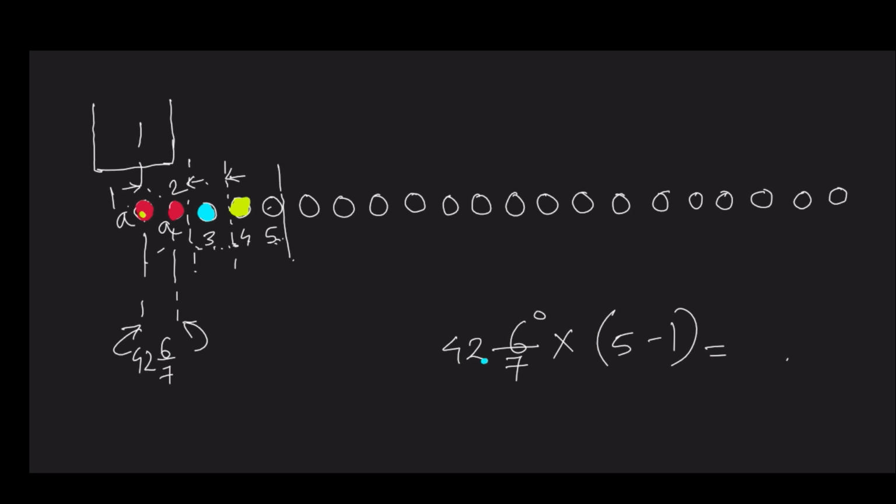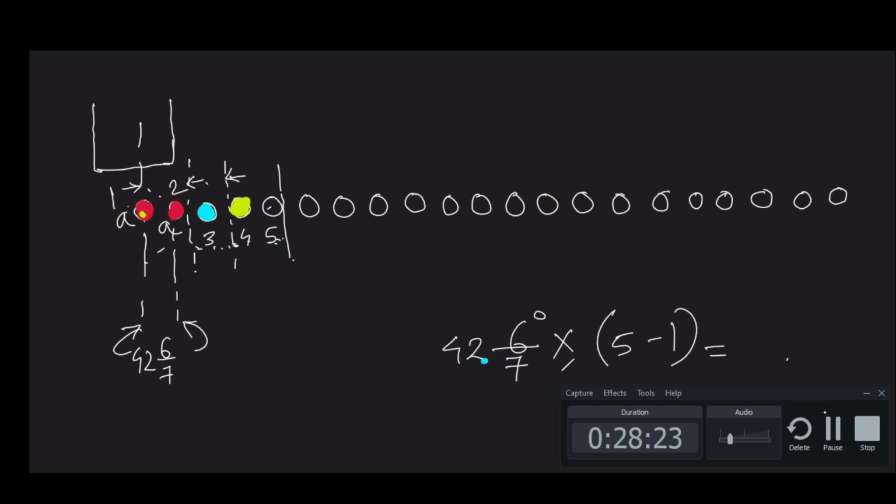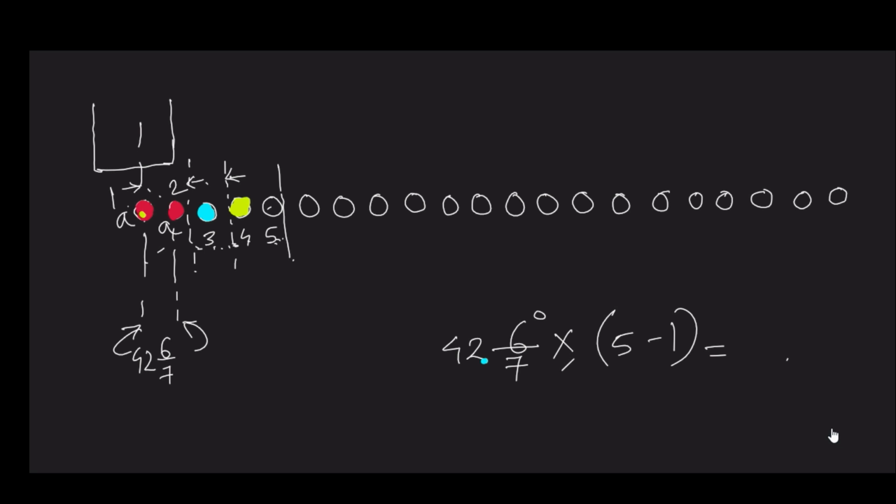They have not written it anywhere. Just let me calculate. So here it is 42 into 4 plus 3, like it is 171 degree, this much degree will get. I am not good at calculation, so I am getting this value. This is still less than 180 degree, so this one should again be filled up with C phase winding, right?